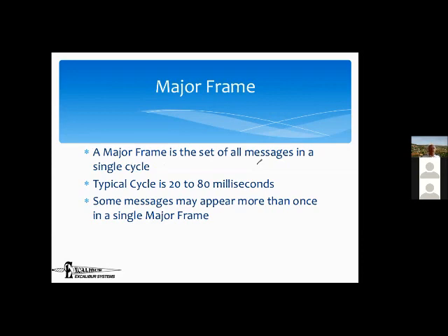Okay, a major frame, which we have seen from the things the customers have shown us, is typically between 20 and 80 milliseconds. And it represents all the messages that are going to go out. Now, you really want a bus controller to be straightforward as much as possible. Theoretically, you could design a bus controller where every cycle is different based on real-time events.